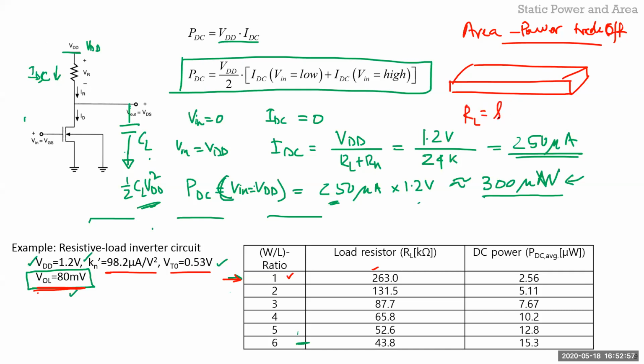RL is equal to row sheet or row poly times L over W. So W you usually keep at the minimum and you keep increasing L. In other words, W times L, the area, is larger for this. Let's say this is some area A. This will be roughly A by 2, this A by 3, this A by 4, and so on. So you get the idea.